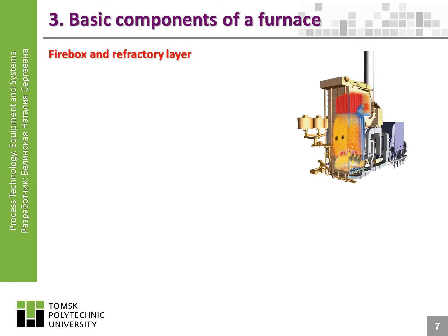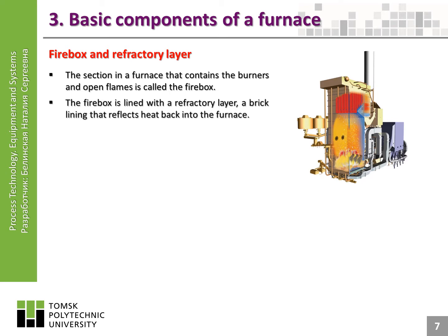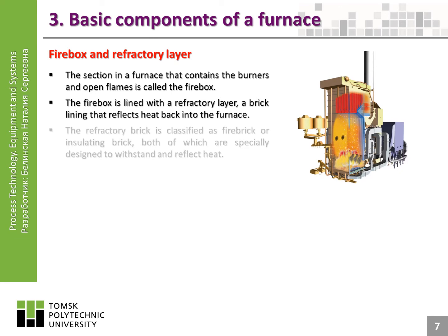firebox and refractory layer. The section in a furnace that contains the burners and open flames is called the firebox. The firebox is lined with a refractory layer, a brick lining that reflects heat back into the furnace. The refractory brick is classified as fire brick or insulating brick, both of which are specially designed to withstand and reflect heat.